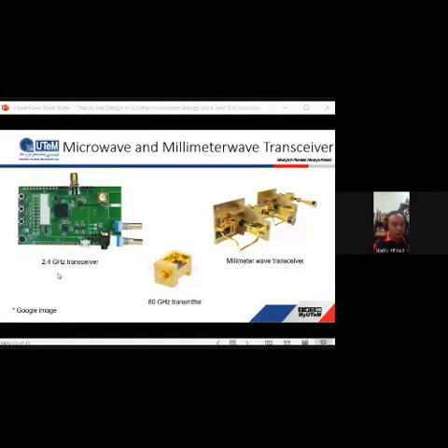So the 2.4 GHz band is a pretty crowded place, because so many applications are now coming into 2.4 GHz. It's used by more than just Wi-Fi. Cordless phones, for example, garage door openers, baby monitors, and other devices tend to use the 2.4 GHz band. And the longer waves used by 2.4 GHz are better suited to longer ranges and transmission through walls and also solid objects.